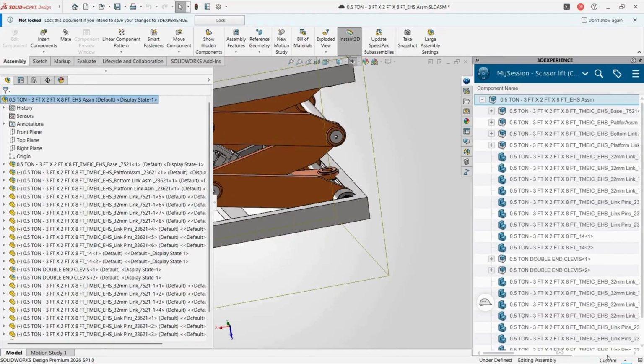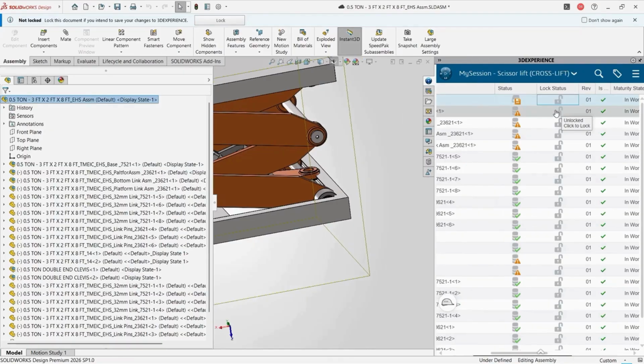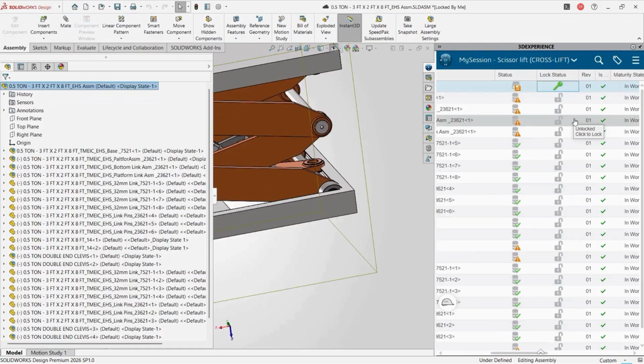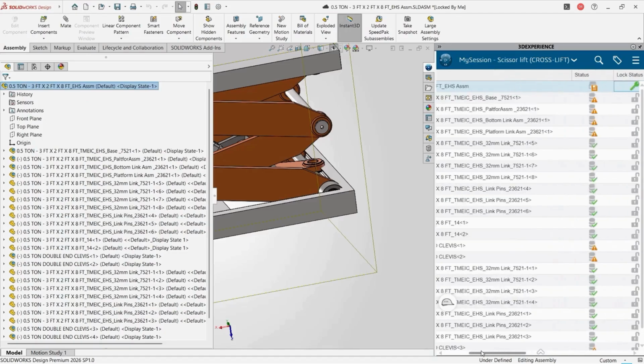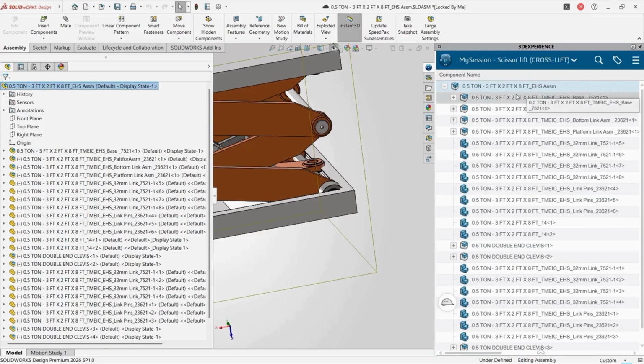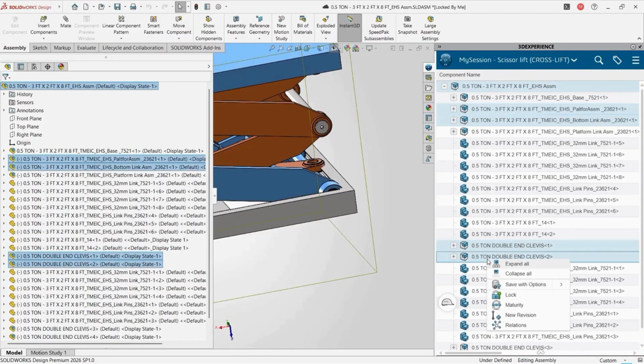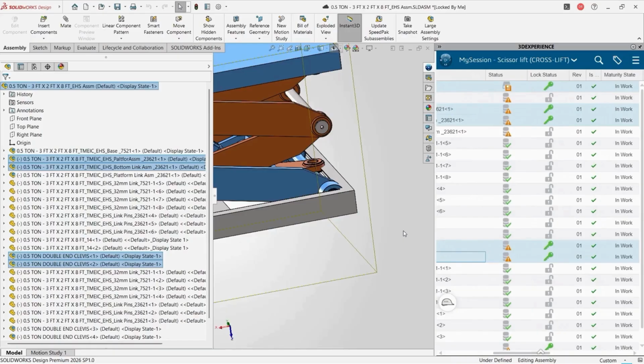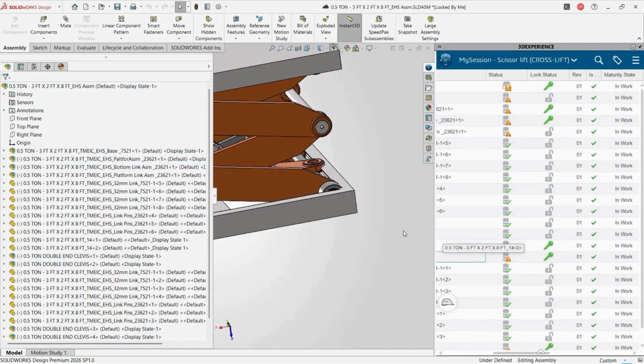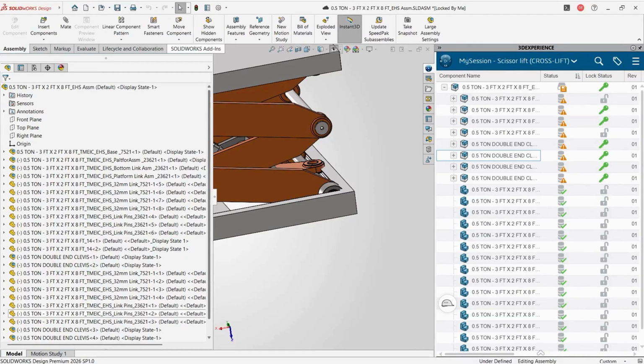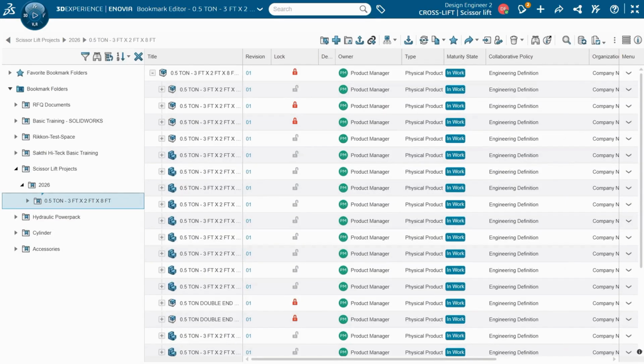So a designer knows from where he needs to start his work, but how does he let everyone know what he is working on in a particular CAD model? In SOLIDWORKS itself, he can reserve the component that he is working on, and that signifies to everyone that the component is being reserved. SOLIDWORKS does that for you with the inbuilt PDM capabilities. As you see, the components reserved by the design head reflect the same to the concurrent user in his interface.